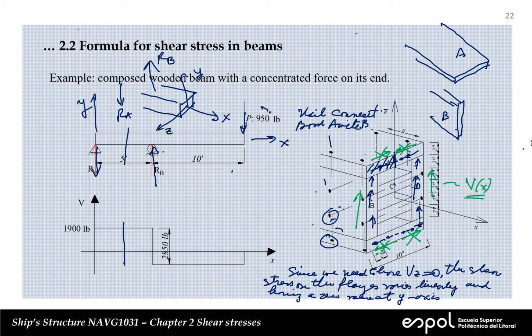So we have to define our sector starting at the point where we want to calculate the shear stress. And on the other side, we have to go all the way up to a point where we know the shear stress. Yes, you're correct. I don't know who answered, but that's the correct answer. We go all the way up to the symmetry line because there, the shear stress is null. Okay, let's do that.